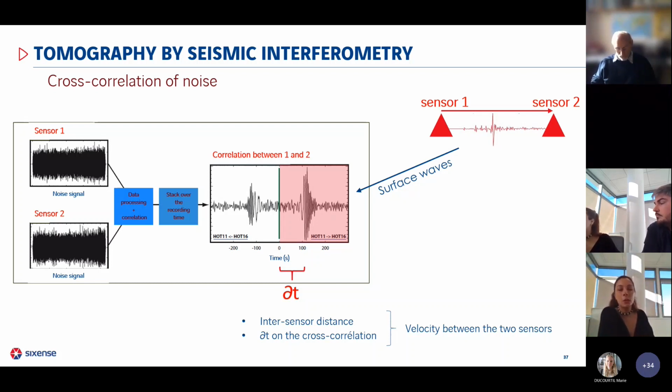We could extract frequencies a bit down to 1 Hertz, and we have data to about 250 Hertz, but then we extract data from the dispersion curves generally to around, let's say, 30, 40 Hertz. So in general, we work between, let's say, 1-2 Hertz and 30, 40 Hertz.